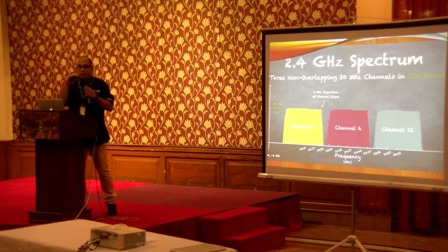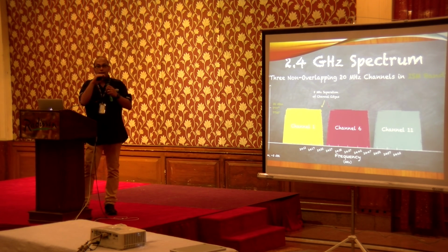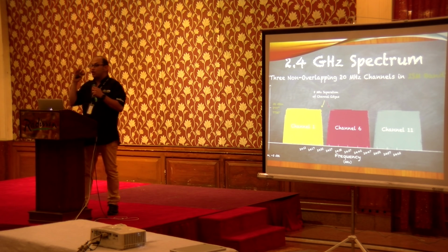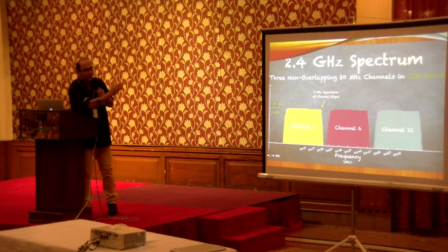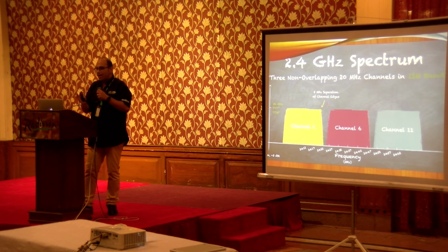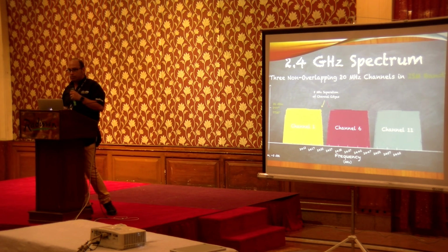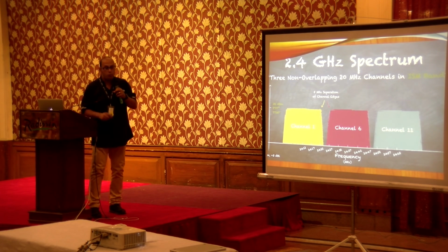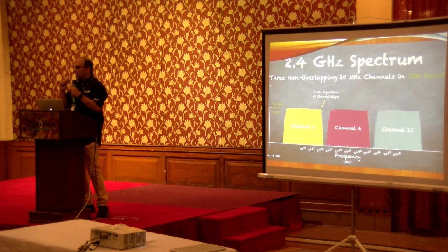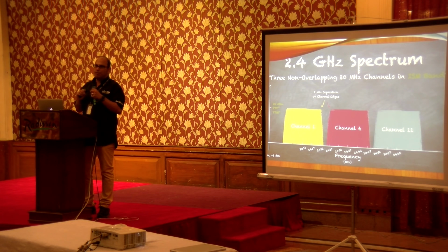The other thing which is very important, you need to calculate channel separation. Channel separation is very important. If you do not have channel separation, you have interference with your neighbors. So, as you can see, minimum 5 megahertz channel separation is needed. Minimum 5 megahertz.